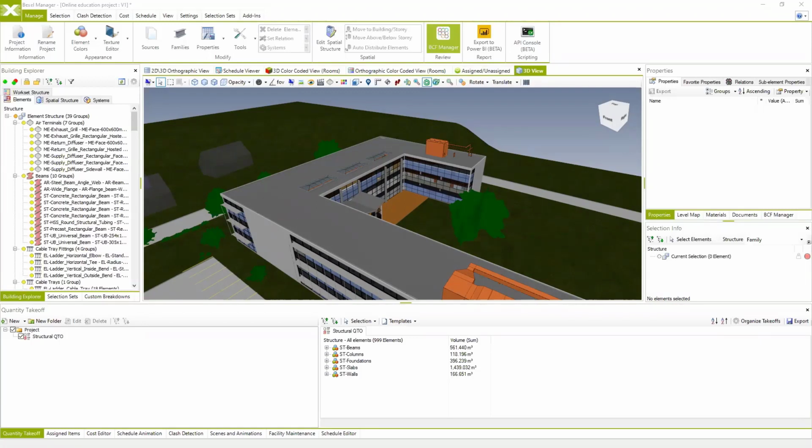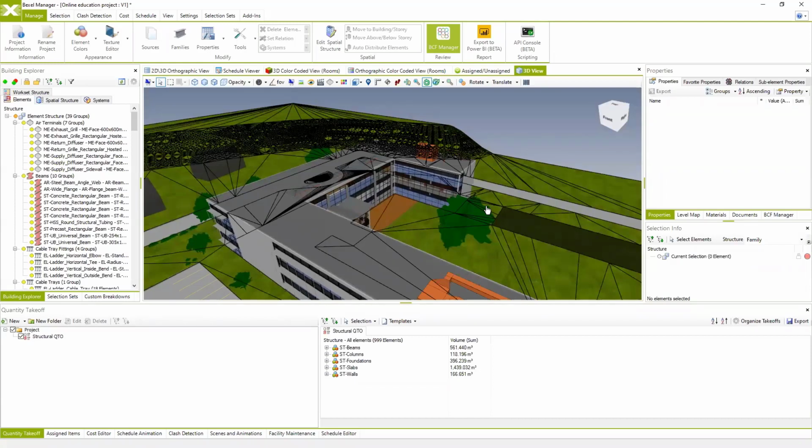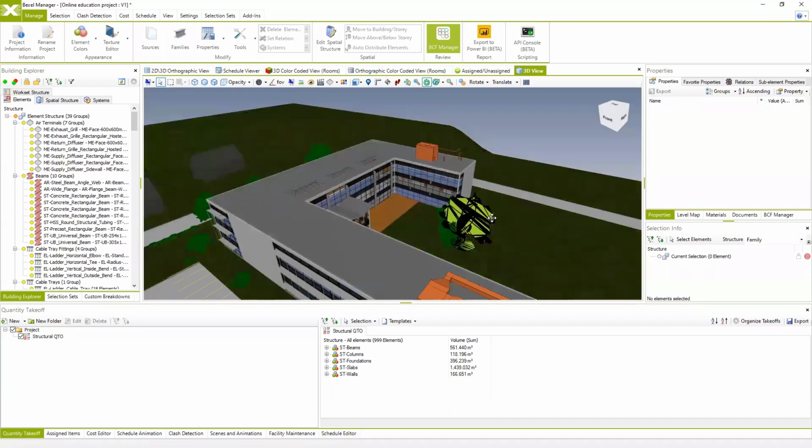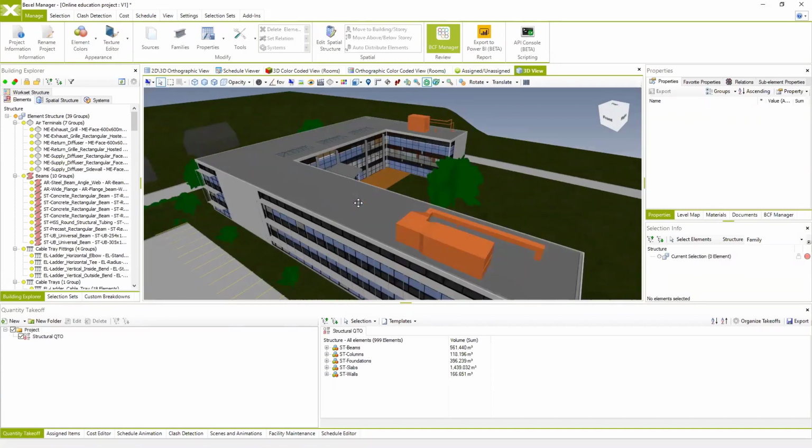And therefore, today I'll show you the basic scheduling options and how to create 4D construction simulation using the schedule generated in some traditional scheduling tools such as Primavera or MS Project, and how to import these schedules into BEXEL Manager in order to link BIM model elements to the tasks from your schedules and to create your 4D and later on also 5D simulations.